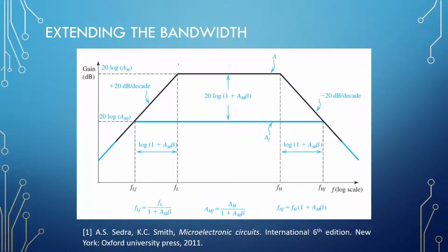As a figure, this black figure here at the top is the gain of our amplifier without feedback applied. Now the moment that feedback is applied, our gain is brought down, but our bandwidth becomes larger. It's not like it spreads into these areas, it's just measured at a different point right here.